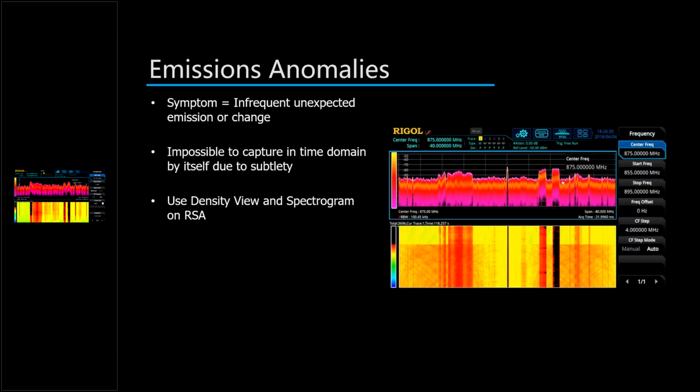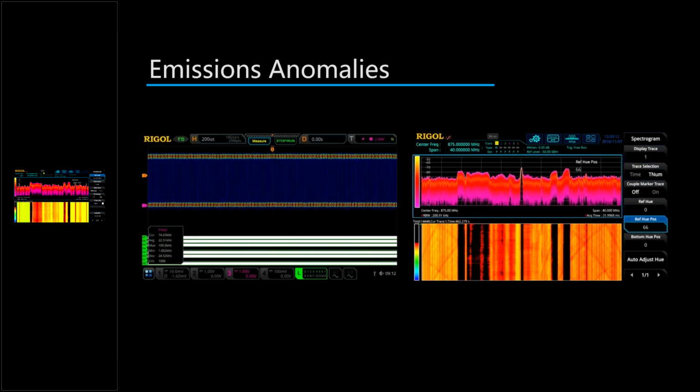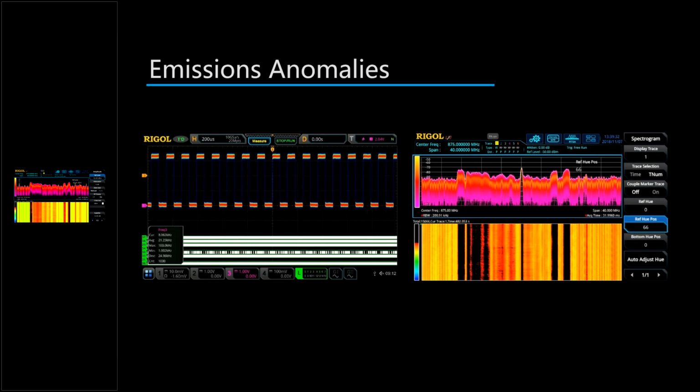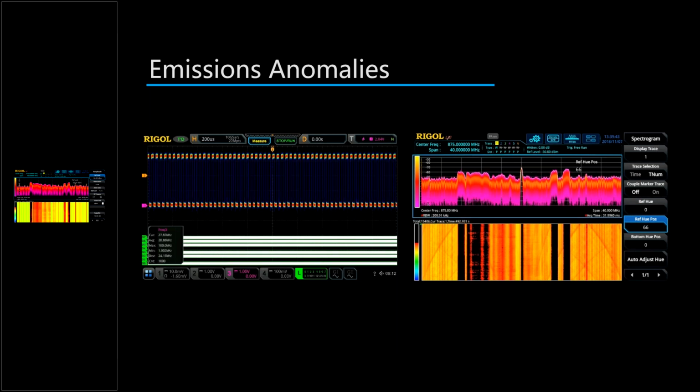Let's look at it now in a video where it's coordinated between the scope and the spectrum analyzer. You can see the reset happening in the middle of the spectrum analyzer. When that reset happens on the spectrum analyzer, we eventually find a line on the embedded board where the scope's also resetting. Here we'll see the frequency reset happening on the scope. In the end we can measure this, and we can see that it's going from about 1 kilohertz up to 100 kilohertz and then resetting about every 30 seconds.